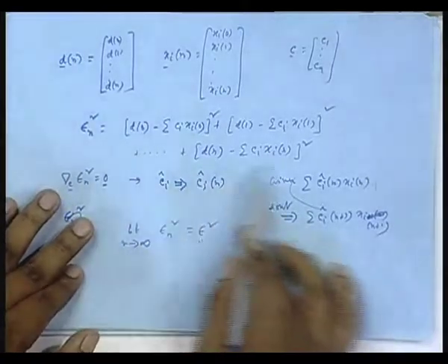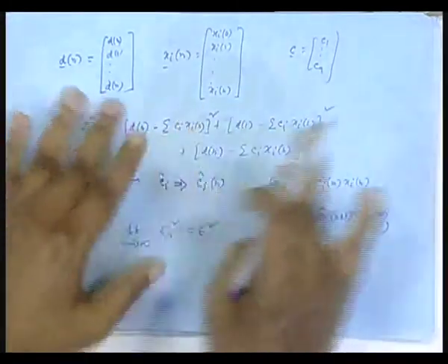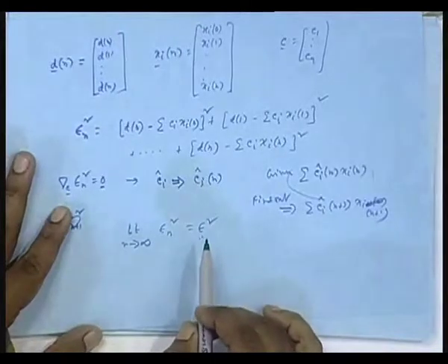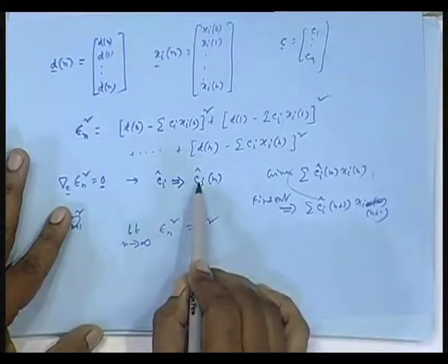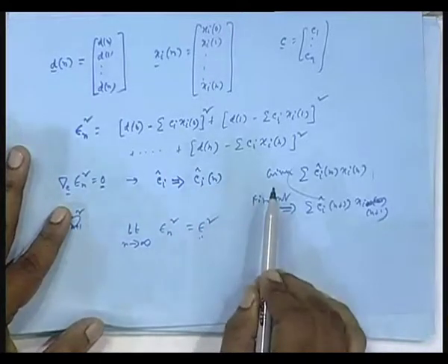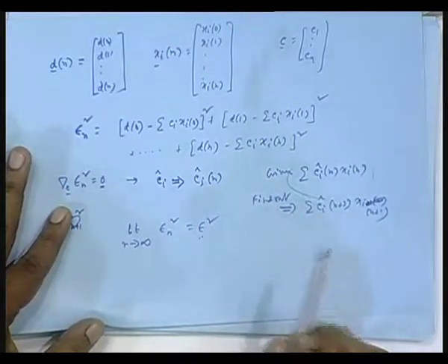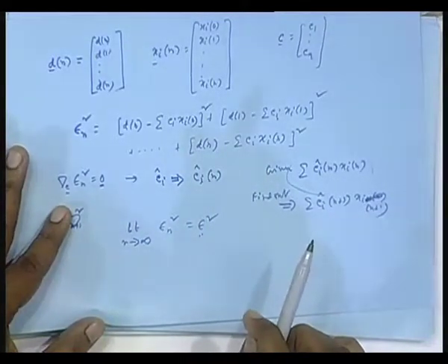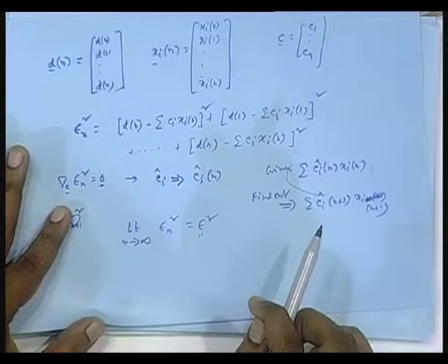But there is no expectation operator. I will take this square and minimize this quantity. So, that means, if I now find a recursive relation for each i, if I recursively can find Ci cap n, then Ci cap n plus 1, then Ci cap n plus 2 and so on, then that will finally converge on the optimal value for Ci, exactly, not in mean and all that.